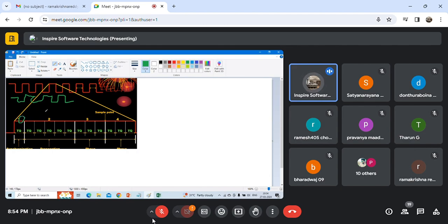When it sees this 0, if it has some kind of offset, the controller logic is such that when you see the dominant bit, and if your dominant bit is not exactly matching the edge, it will skip some of these time quanta.